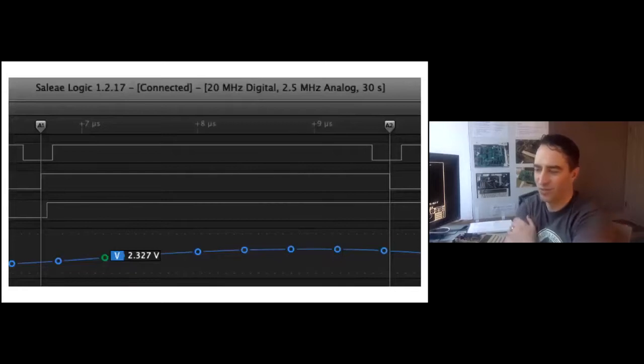Here's a view of what was going on. This is basically the hack that I implemented to make the keyboard work, which was to massively stretch out the clock cycle. It's out to about 3 microseconds when reading the keyboard, because it took quite a lot longer than it was supposed to rise back up to a 1 level. So this made it work.